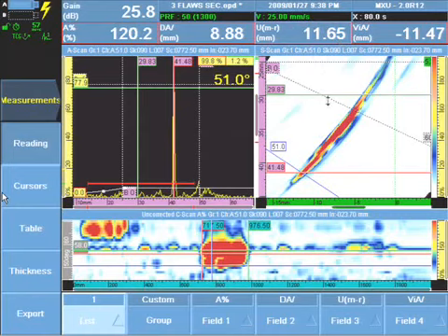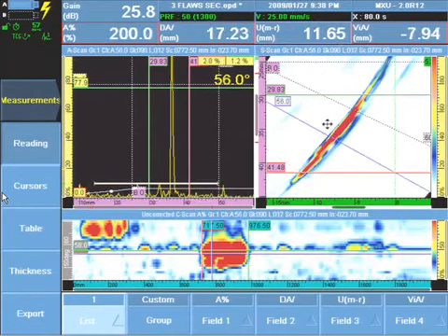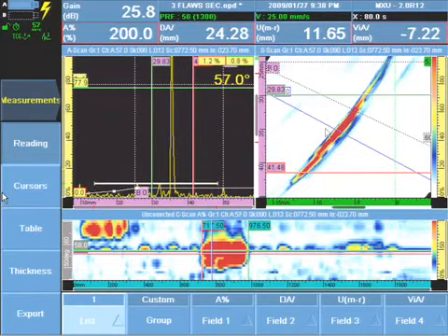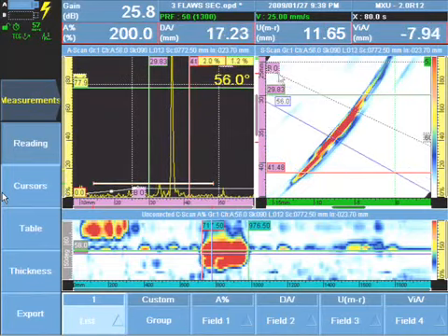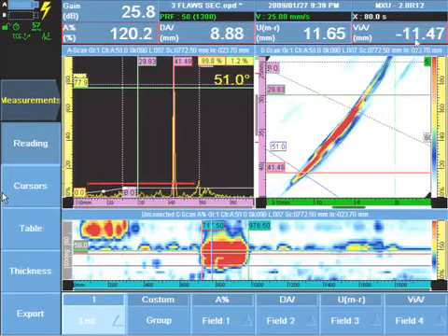We have sidewall lack of fusion at a depth of 17 millimeters with a through wall dimension of 11.65 millimeters, the center of the non-fusion at minus 79 millimeters on the skew 90 side of the weld center line, and the top at 11 millimeters from the weld center line.